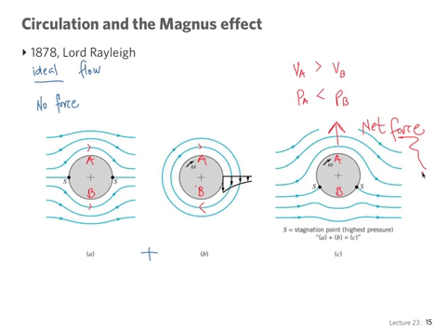Does the distance of the stagnation point decrease as angular velocity increases? The stagnation point, yes, you're right, S is the stagnation point. Because of the added effect of the circulation, the stagnation point in the front has moved to a little bit lower point. The one in the back has also moved. They both are closer to point B, and if you have a bigger and bigger circulation, these two points are closer and closer to B. Okay, correct.